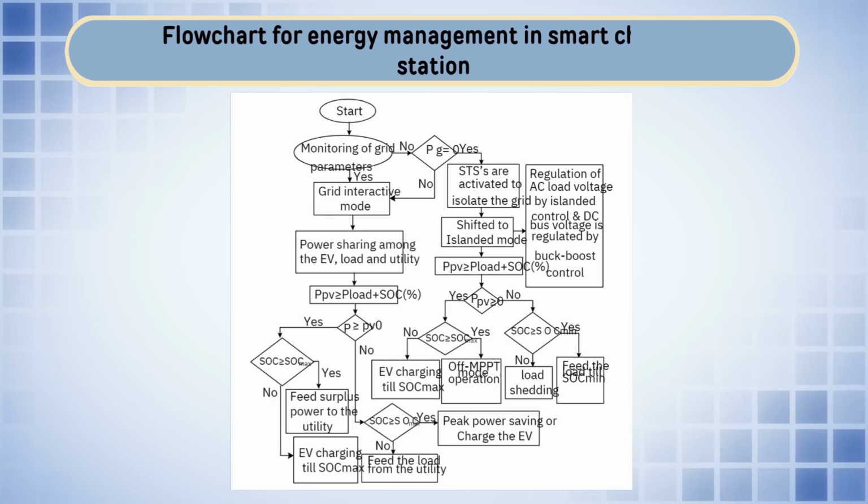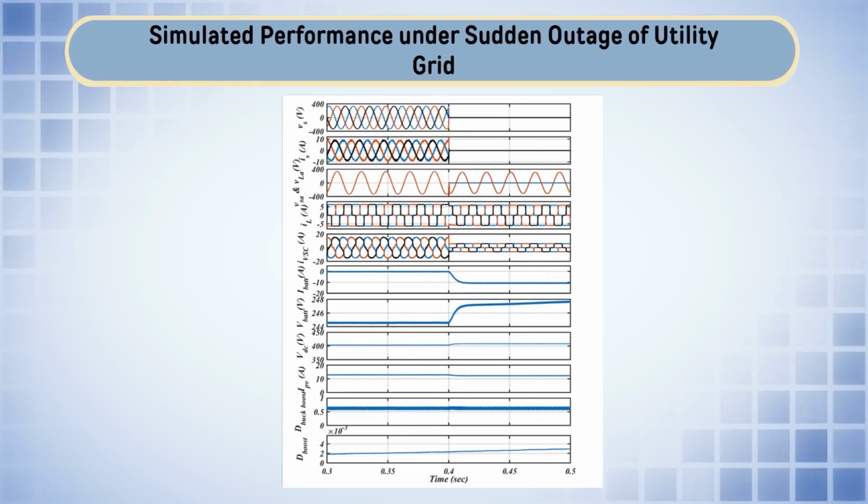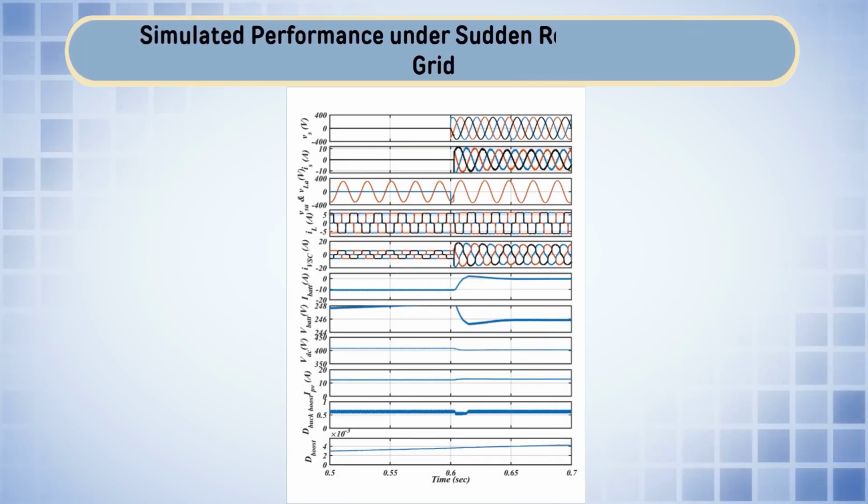So, at a certain time instant, a grid appears. Under this condition grid voltage and currents are there, and accordingly we can switch the battery. Suppose in this case of standalone the charging was required, so battery current was negative. As soon as the grid is there, considering the SOC of the battery is maintained, the battery is switched from charging to the floating mode.